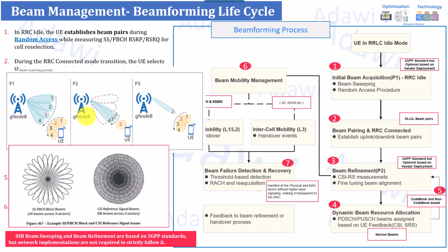So now, for example, if you have 8 beams in the cell, as shown in the bottom left figure here, 8 multiplied by 4, you will have around 32 CSI-RS beams within the complete cell. So it will look like this at the very end for the complete site, which is 3 sectors.